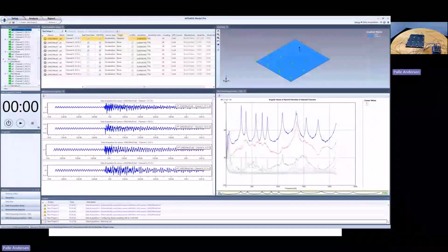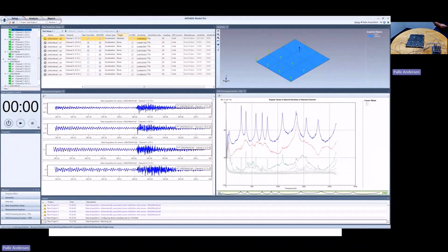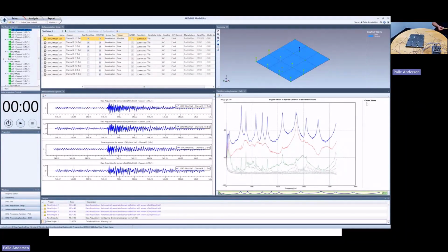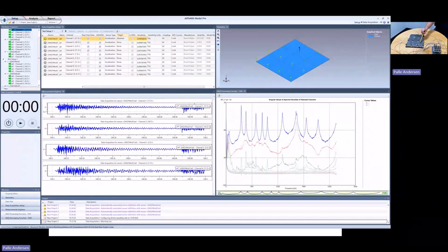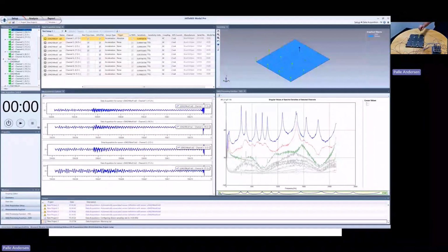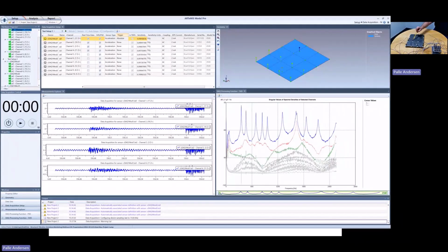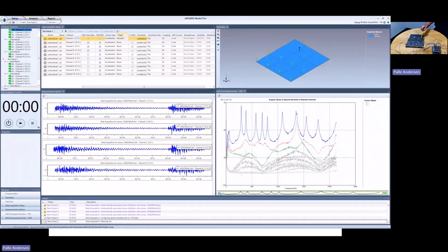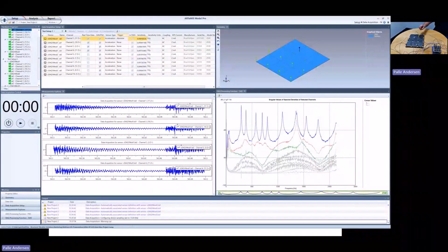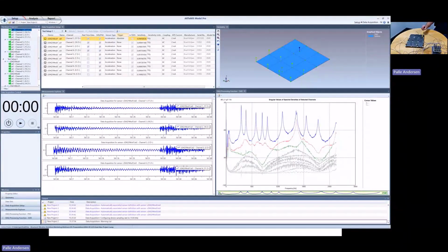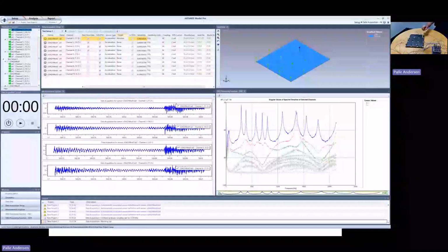And this, of course, brings me to how we should now test if we want to produce a diagram with multiple inputs. What I can do is I can simply do like this. If I now hit all randomly places on this structure here with my pen, you can see how all the other singular values are now also popping up and helping us to much better understand the dynamics of this structure here, and of course also helping the analysis to become better.